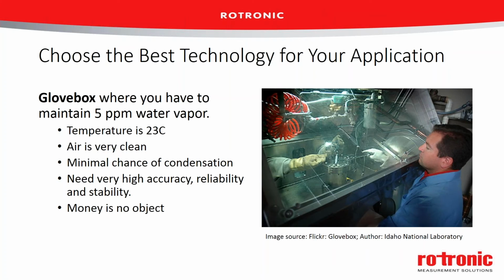So given that we're talking about low humidity values, we're looking at either chilled mirrors, capacitive sensors, the ones specifically done for the low humidity values, or potentially metal oxide. I would take off the metal oxide right away, just because we probably want something that can respond quickly.